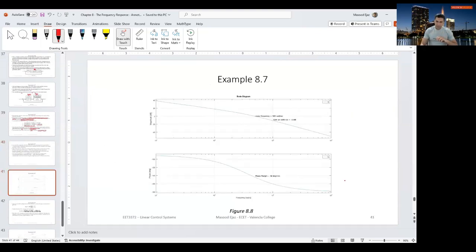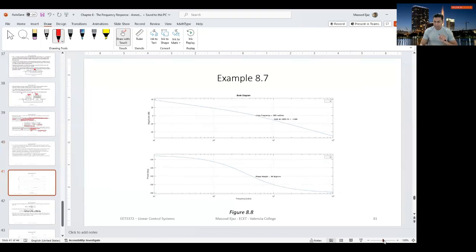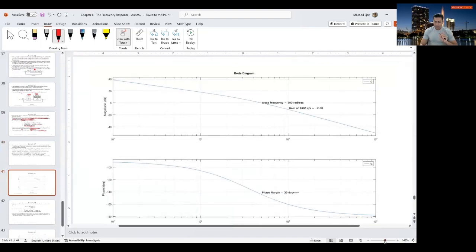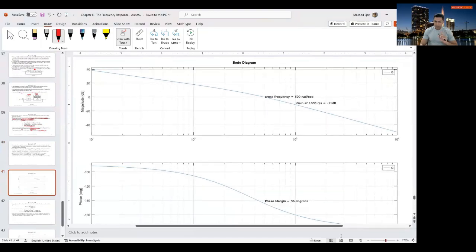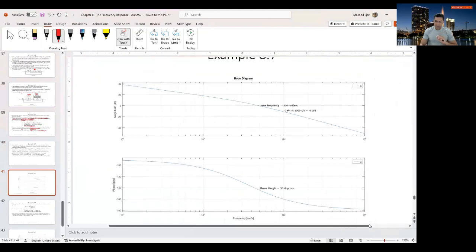So let me go to, so I created this plot using the Bode function. So this is exact Bode plot, it's not approximate. Remember, Bode plot is approximate. All the approximation that we have learned, that is used in Bode plot. Now the Bode function in MATLAB does the exact Bode plot. That is, it takes 20 log, whatever, 1 plus whatever, and then changes the value of omega, and then plots the exact Bode plot.